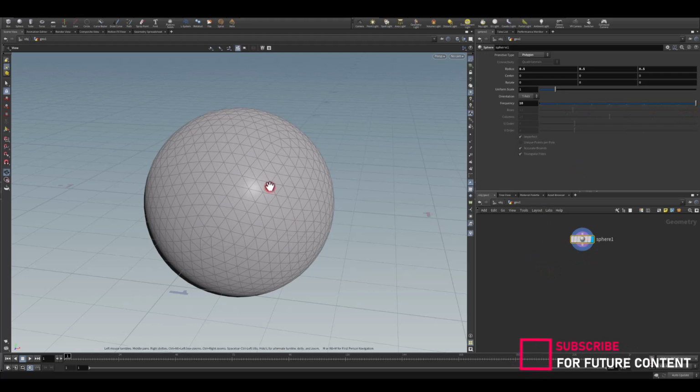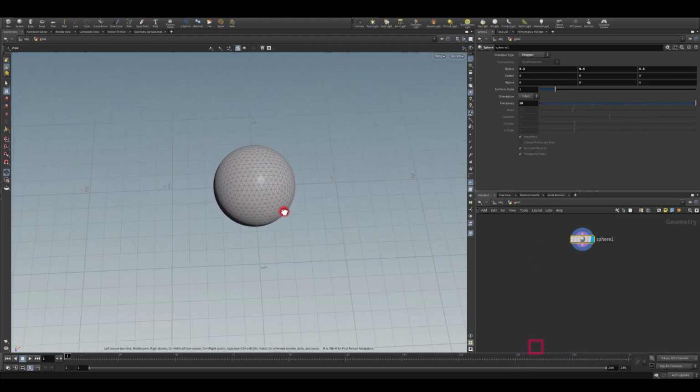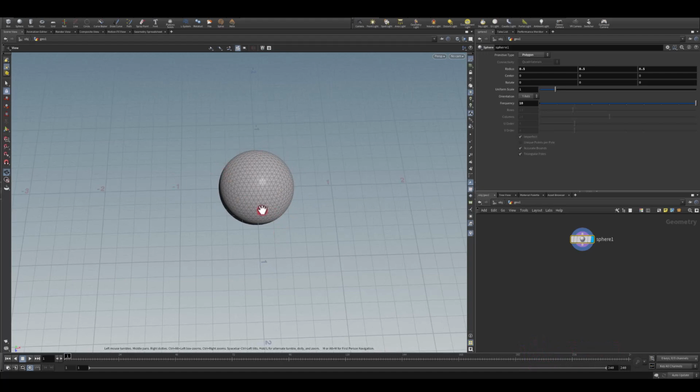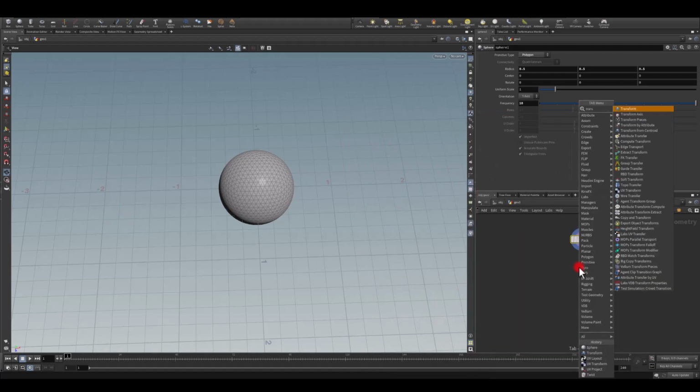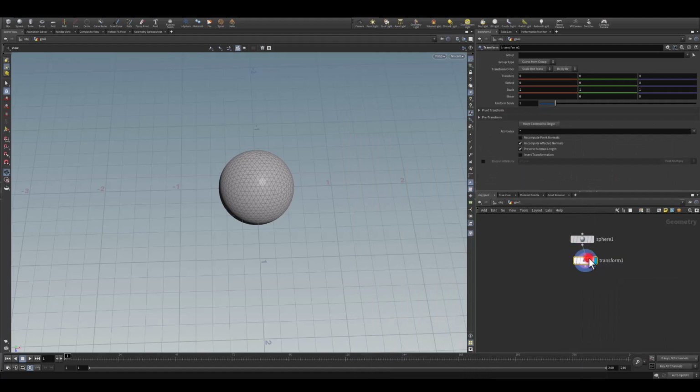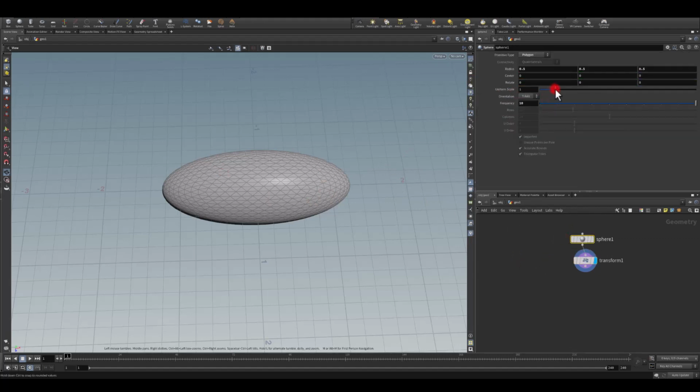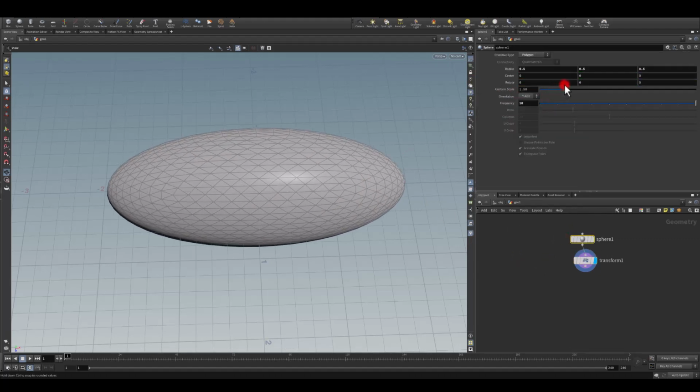And next, I would like to scale it up a bit, because right now it just takes a little bit of space, but I think I want it to be around maybe values of 2, because I'm going to stretch it later with the transform. So let's get transform next. In here, I'm going to stretch it maybe to 2.4 or 2.5. And now I want this to be a bit closer to the value of 2, so I'm just going to start increasing here maybe to 1.5.